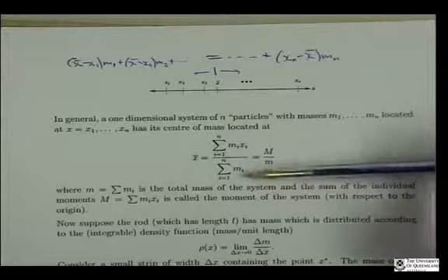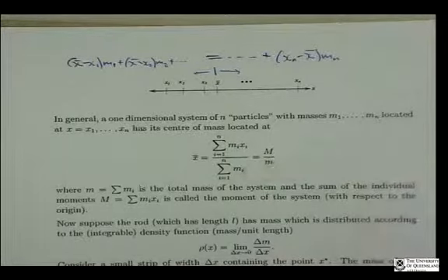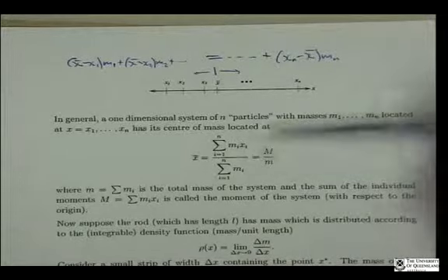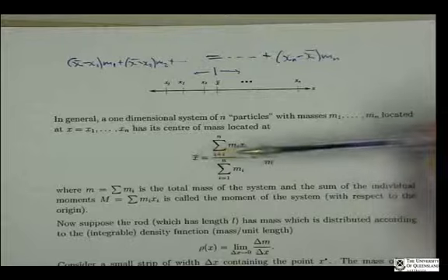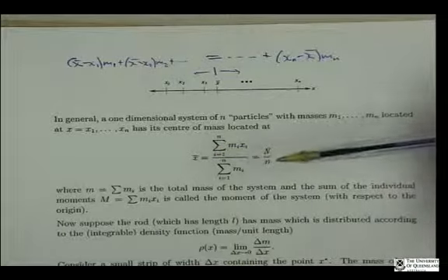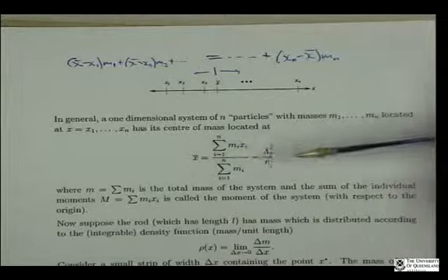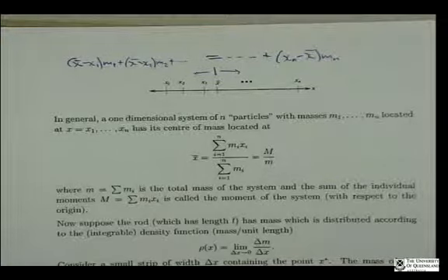And in the denominator, we have just the sum of the masses. So in other words, the total mass of the system in that denominator. All right, so this is for n particles. So you can see for any number of point masses here, we can obtain a formula for the location of that fulcrum in the law of the lever. So this is what we'll call the center of mass of the system. All right, that coordinate x bar. And so this is what we hope to develop in the two-dimensional continuum.